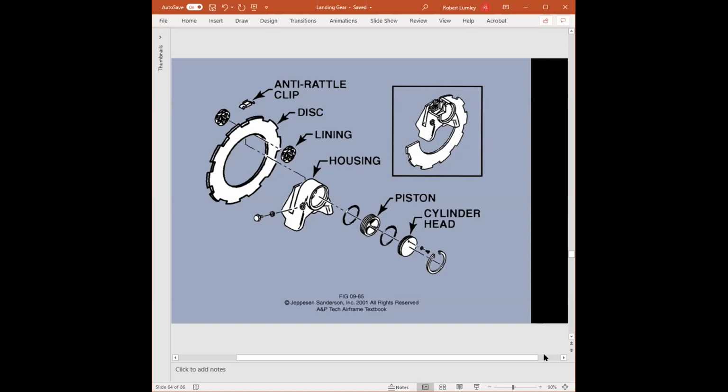And yes, does it work? Yes, it does. But hopefully we can see a problem. You just put grease on the brakes. Now, initially the grease isn't there, but once the brakes get hot, that grease is going to start moving around. It will get onto the discs, and now you have greased up your discs and pads, and that's a bad thing.